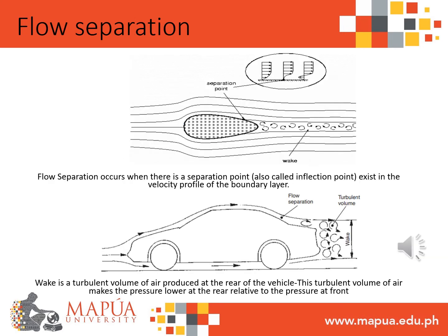Moving on, I will now be discussing flow separation. Flow separation, or boundary layer separation, is a term used when a boundary layer detaches from the surface and the fluid starts to flow in reverse direction and turns into wake. Flow separation occurs when the area of the flow widens, which will cause a decrease in speed and a pressure rise.